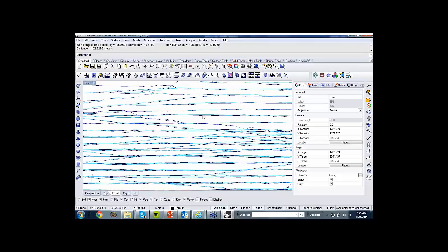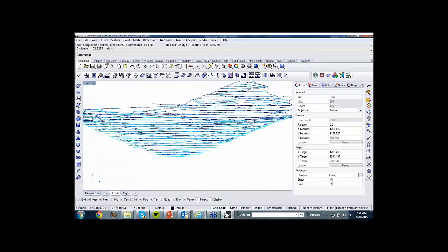So if you sample these curves at a distance of more than 18 meters, it's going to create an aliasing effect. Basically, it will not see these shelves, and it's going to produce a lot of noise. So you want to sample them at a distance shorter than the average height between these curves, and then you can be sure that you obtain a nice and smooth representation.